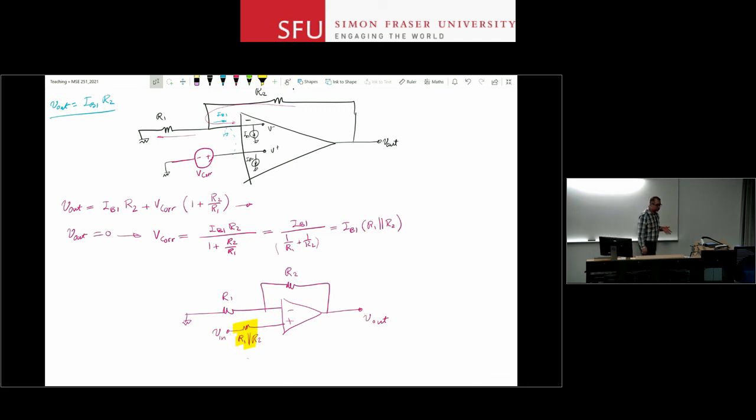But most of the modern op-amps, I would say almost all of them nowadays, almost anything that you buy off the shelf, has a current limit. So this is another parameter that you should look up on the spec sheet. If you want to drive a load that needs 100 milliamp of current, well, can your op-amp provide that much current? Because they have current limits for their protection.